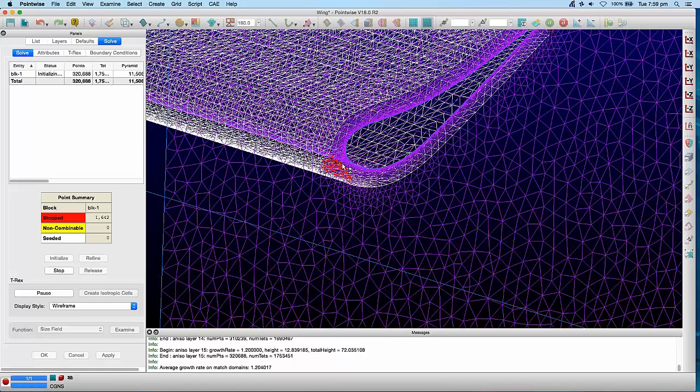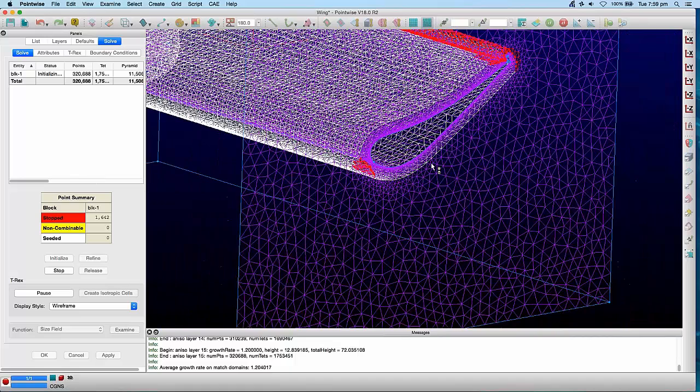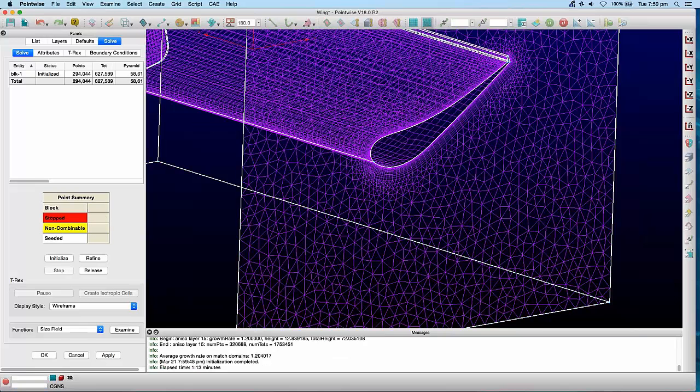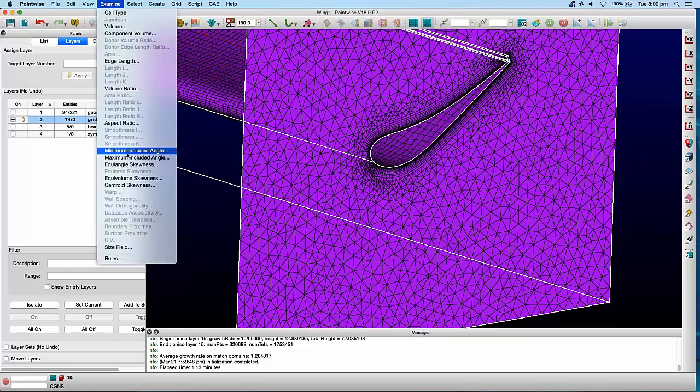So at this point, T-Rex is just finished, and Pointwise is now just generating the volume mesh. It's going to take an extra minute or so. So at this point we can come across here and say we've generated a total of 845,000 cells, 235,000 of those was in the boundary layer region, so from T-Rex, and we got 7 complete layers, but a total of 15. So the complete layers would have been up to the point where they stopped, and then after that it's just partial layers.